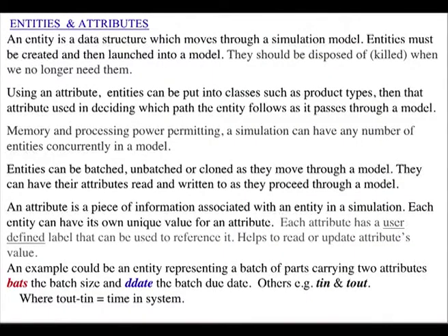Entities and attributes. An entity is a data structure which moves through a simulation model. Entities must be created and then launched into a model. They should be disposed of, killed, when we no longer need them. Using an attribute, entities can be put into classes such as product types, and that attribute is used in deciding which path the entity follows as it passes through the model. This was done in the ShowFlow model.